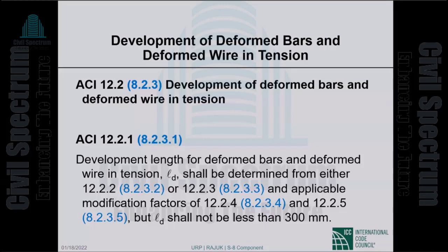That bond is low, very easily overcome. That is why, already in the 50s and 60s, we switched to these deformed bars, where the ribs on the bars greatly improve the bond between the reinforcement and the concrete. Today, basically all reinforcing bars are deformed.